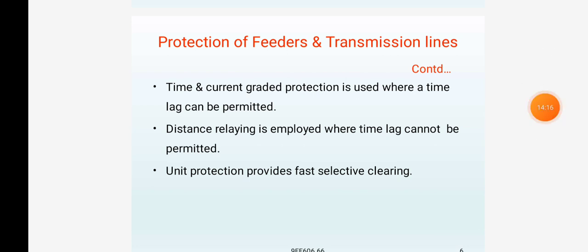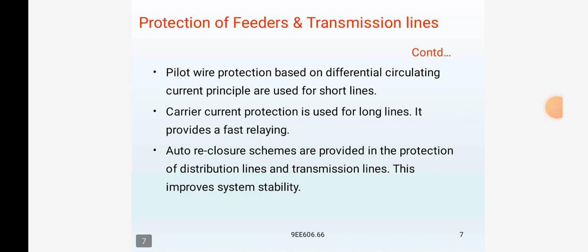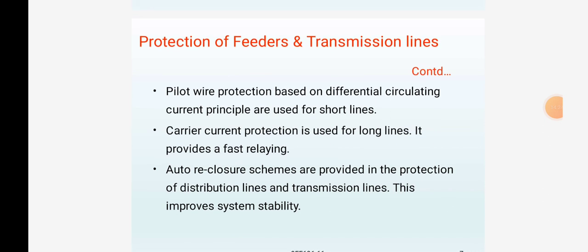And also we have the duplicate bus bar. In duplicate bus bar, the plant is split into two entirely separate systems which can be worked at different voltages if desired. If both LV and HV bus bars are not required, high voltage bus bars alone may be duplicated. This is the most flexible layout and is meant for large generating and or transforming stations.